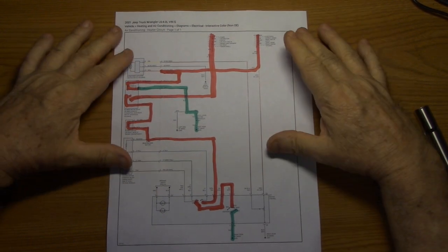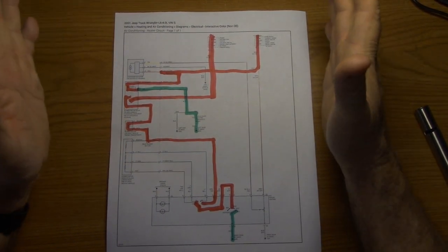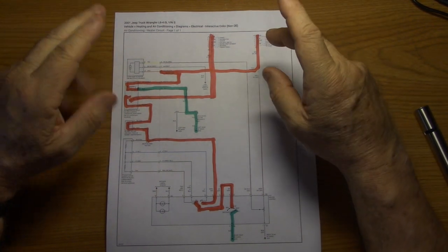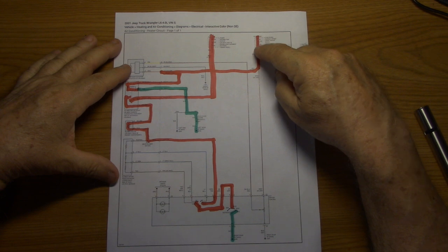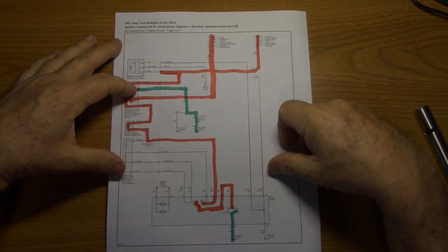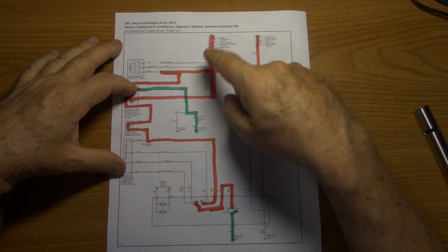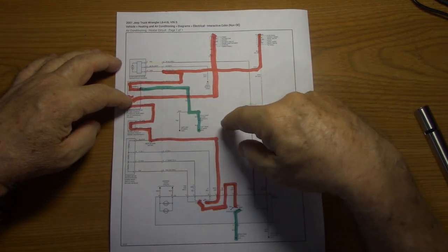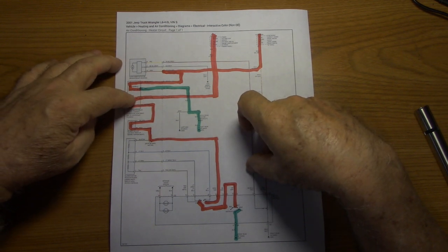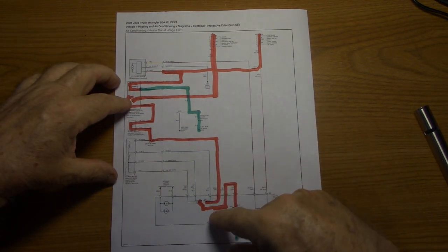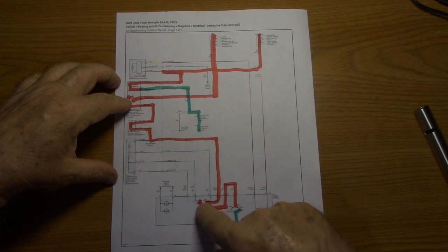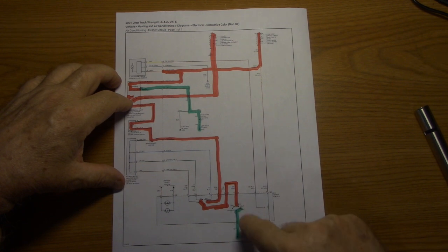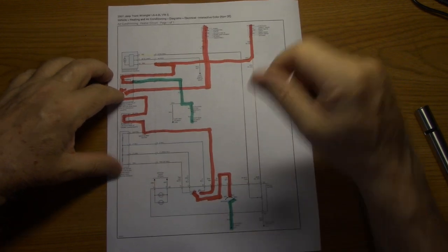So just to recap, I want to make sure I'm not confusing anybody. We have two circuits and we want to make sure they're both good. The one switch circuit provides power to the blower motor relay and closes that when you turn the switch on. And this constant battery power that's always there, once this switch closes, it'll feed power all the way through to the speeds on high. It'll go straight through the speed switch, and then to the mode switch, and then to ground.